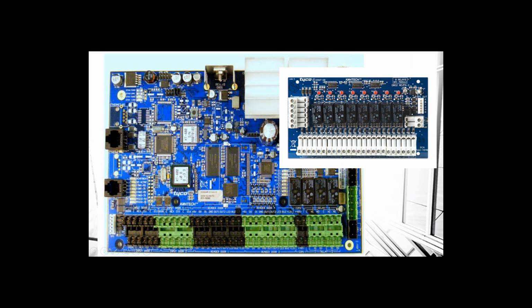How to connect those? The KT400 has an SPI port. On the left here, we see the SPI port. We'll take a look at the installation we have here. We're going to have a cable going from the SPI port to the relay module. Pretty much that's it. Of course, we need to get the controller itself installed, programmed, and communicating. Then we install the relay module, we define that, and we move on.